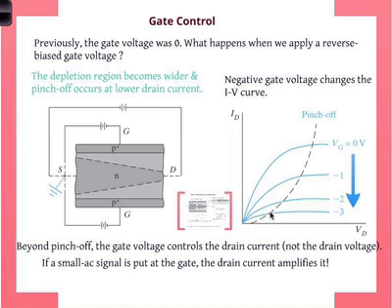And there, if you look at the pinch-off point, you can see there's a nonlinearity. It's a square dependence. So a small change in gate voltage, let's say going from -3 to -2 volts, has a pretty large change in the current. Not shown here, but you saw the numbers last class. So that's where the amplification comes from. A signal that goes into the gate with a small amplitude comes out as a signal in the current with a large amplitude. And that's the gain. The gain happens from the input control voltage to the output current.